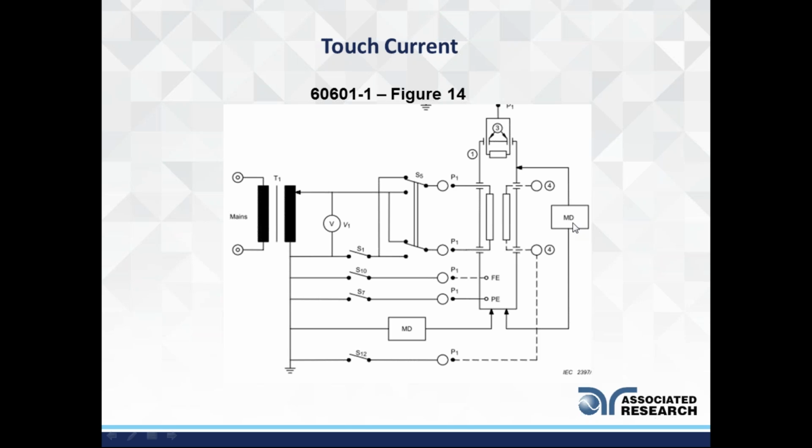Okay, I have another MD over here. I have it between two touch points on the medical device. So you might need to run that test as well. So that's touch current. We kind of understand that. I have my transformer here that's powering up my MD, in the standard, at 110% of your rated voltage at its rated frequency.